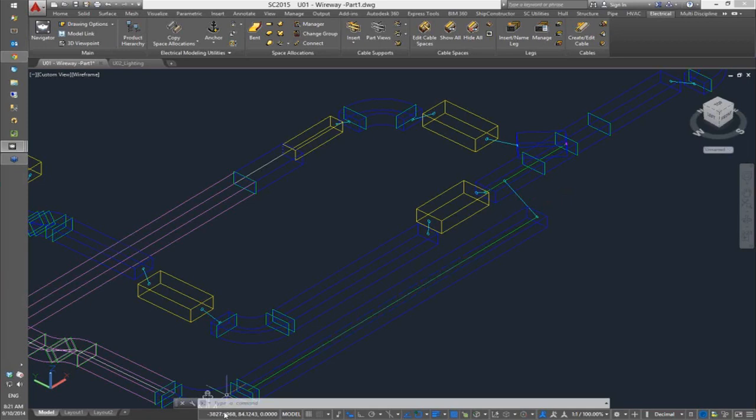So if you're going around a bend and the cable's on the outside of one, goes into a T and is on the outside of the other, it will be quite a different radius than if it's along the center or towards the inside of that corner. And also the person laying the cable has options such as bending the cable before it actually reaches that corner.